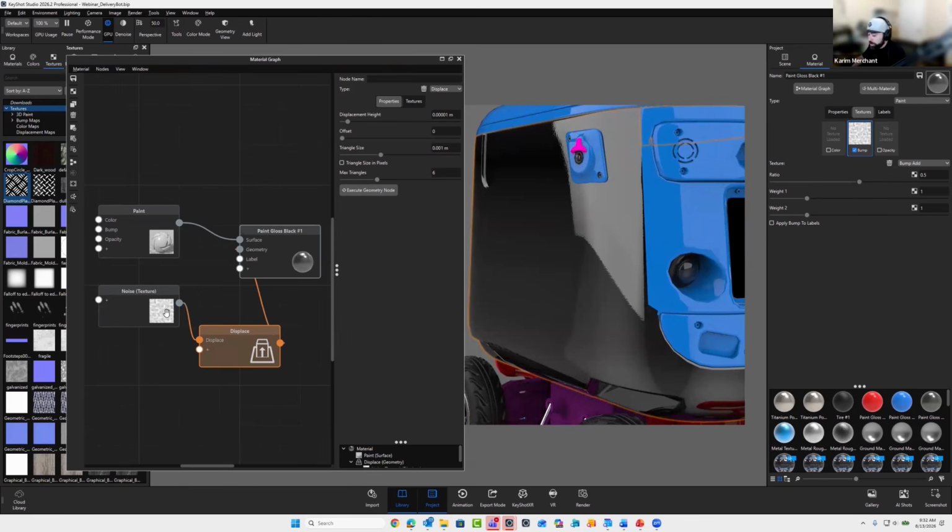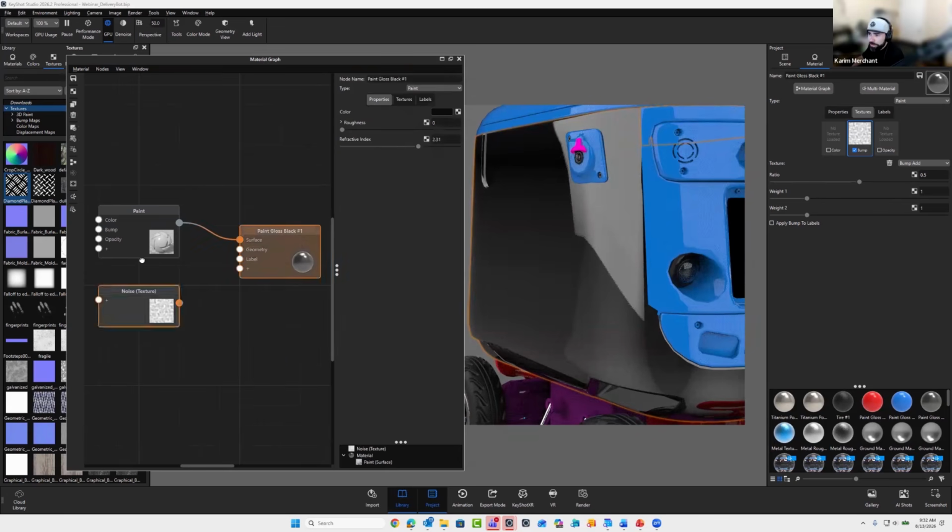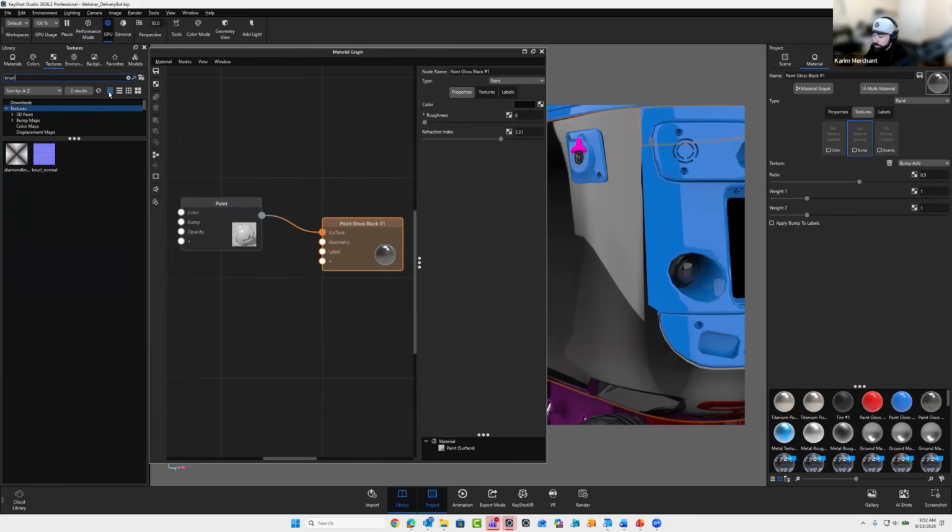So the reason why I brought this up specifically is that when I look inside of our textures over here, we have something for knurling. Knurling can sometimes be difficult to CAD model, or it's time consuming. But in this case, you could use the knurling to drive your displacement. You could create a bunch of parts that have different knurling depths and different scale.